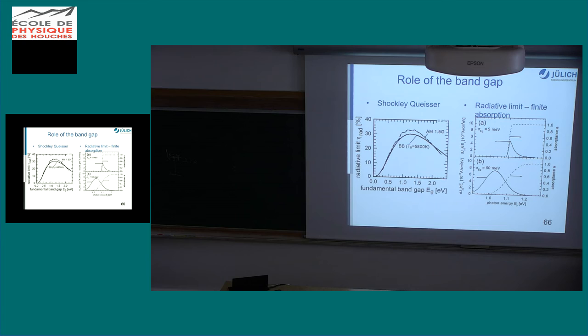So that's a small modification to the Shockley-Queisser approach, still radiative, but just assuming not a single band gap, but a little bit of disorder in the material. And you see your loss gets much larger as compared to the band gap, average band gap still unchanged. Just because of the disorder, you're getting more losses.